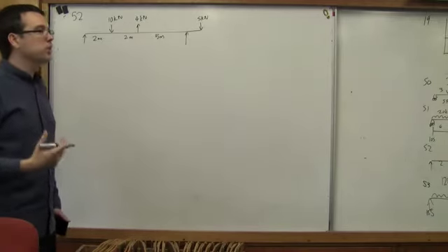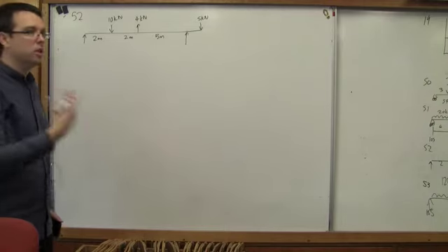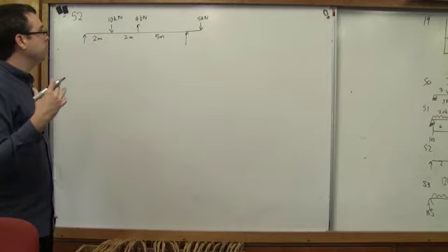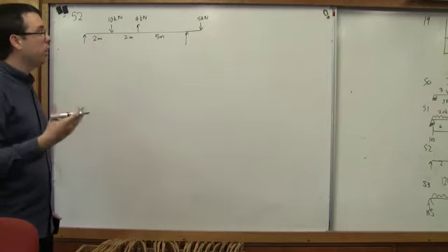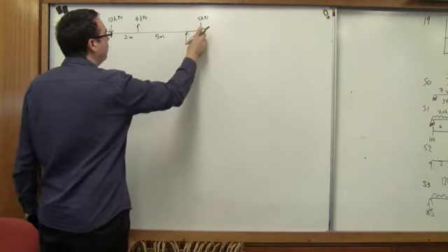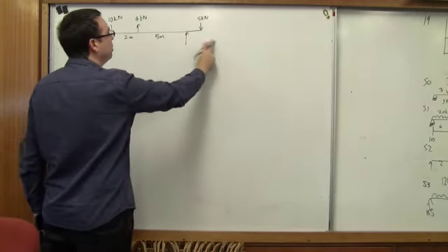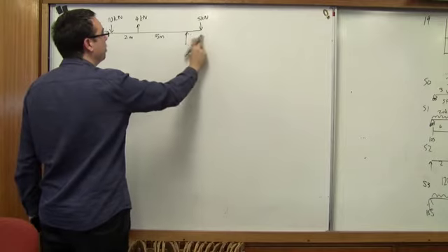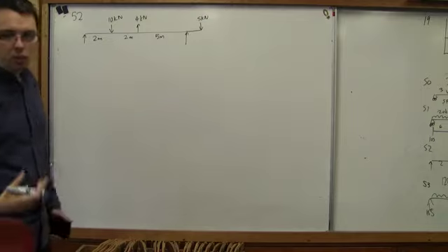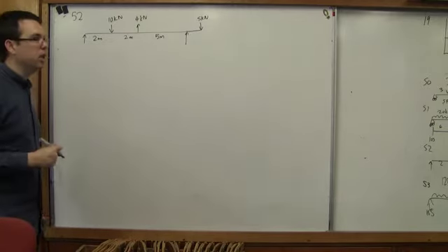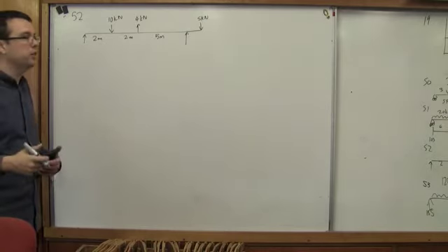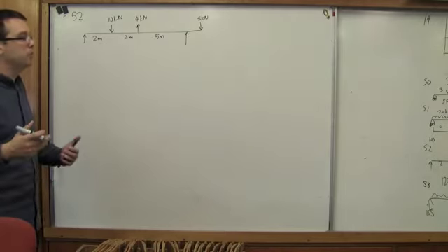Just as a convention, we like to find the roller first by taking moments about the pin. But if there's no horizontal component, it doesn't really matter. Here, we have a force that is extended out beyond the reaction, which means this is a cantilever. Copeland has said that he is a big fan of cantilever questions. He doesn't write the exams, but he is definitely influential, so keep that in mind.